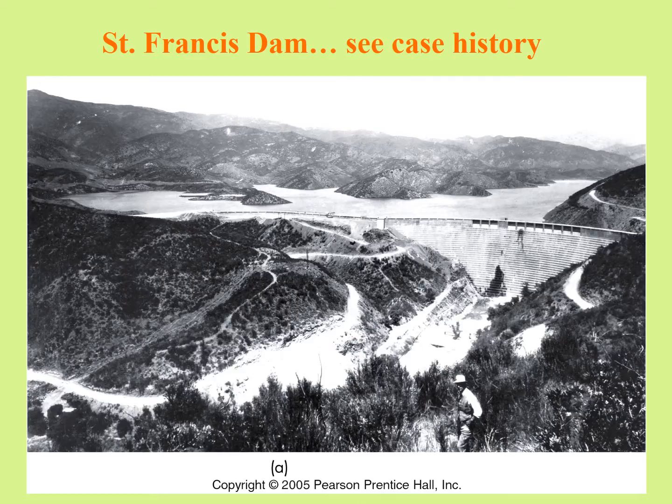Looking through the engineering experience in the United States, we can see a very infamous example of a dam built on a metamorphic rock in southern Los Angeles. And if you ever watch the movie Chinatown, they don't talk about this application. They hide the truth and make up a different project. But back in the 20s, as part of a process to get adequate water supply for Los Angeles, the St. Francis Dam was built. The only problem was that it wasn't built by an engineer, and it was built right on some metamorphic rock that was a poor choice for the foundation of this material.